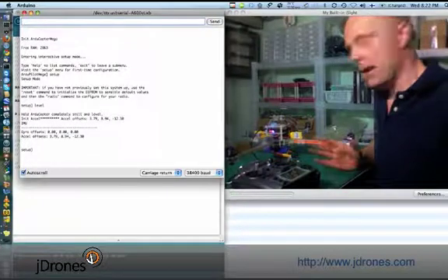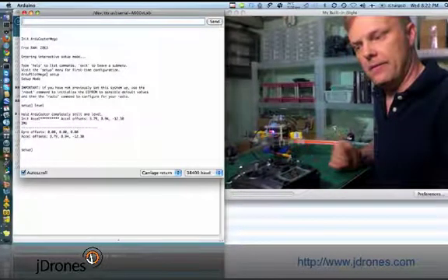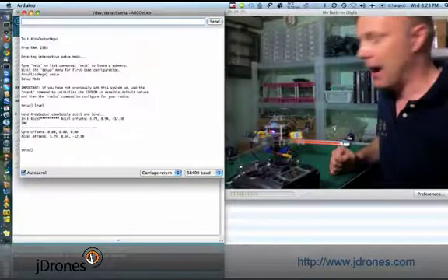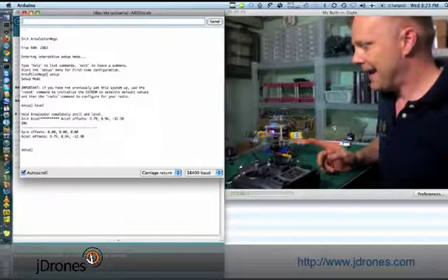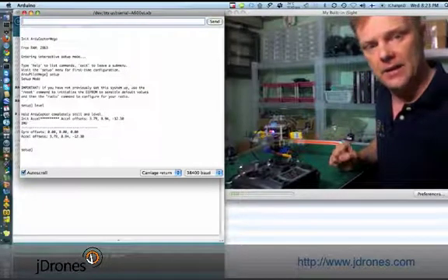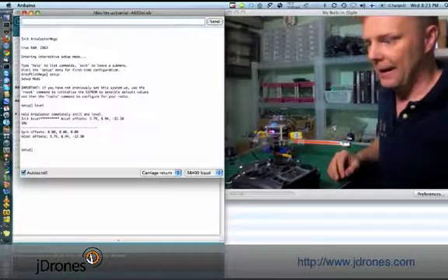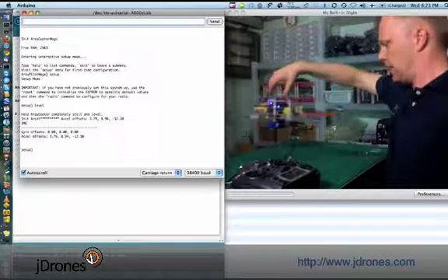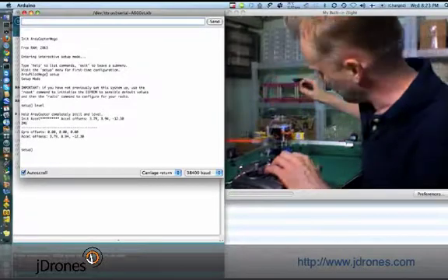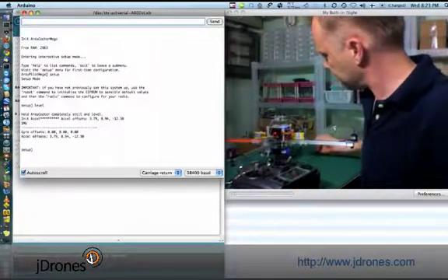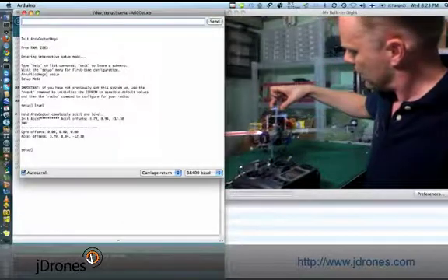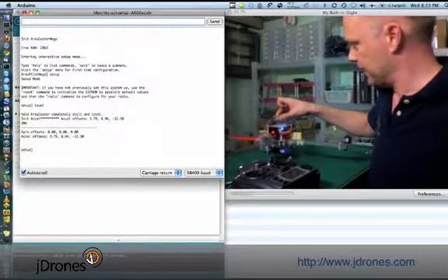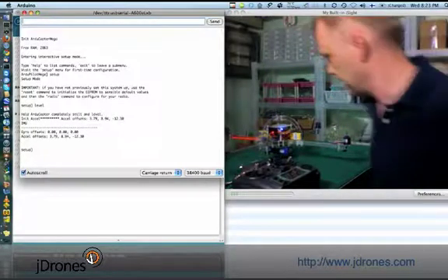Yes, when you're having this kind of a sound coming out from your motors, it means that none of those ESCs are calibrated. So we have to calibrate them, but first we have to calibrate the radio. Do we have a radio signal now? Now we have a radio on the receiver. This is just one of my test receivers, so it's a little bit shaky.